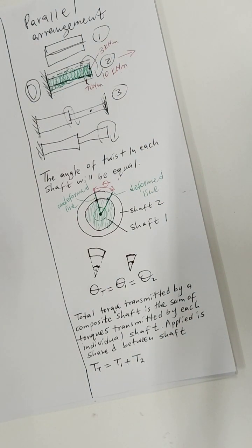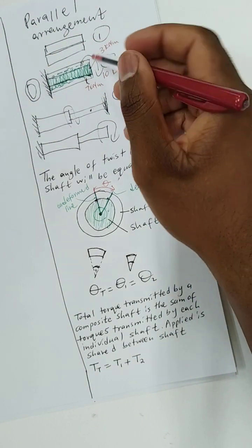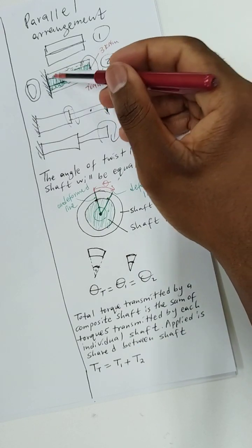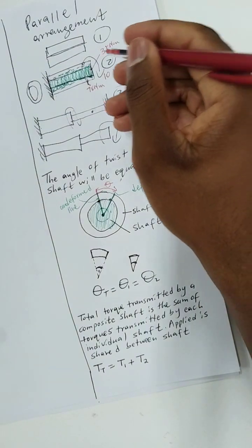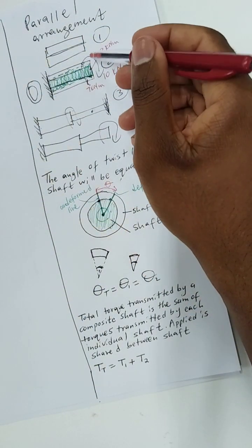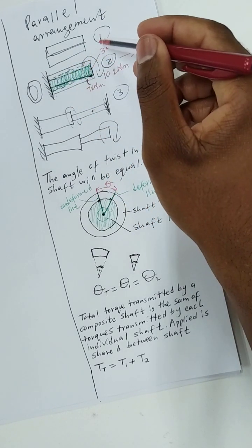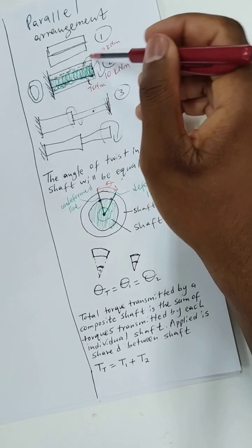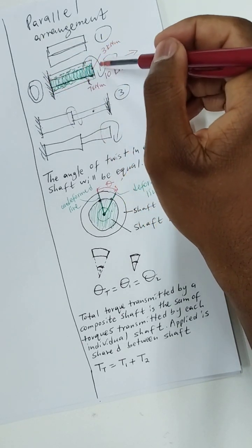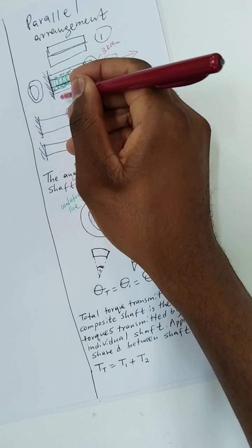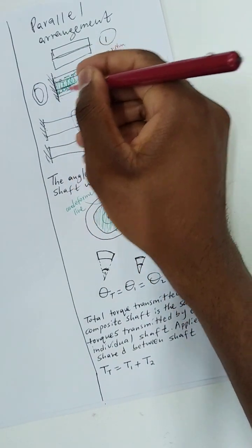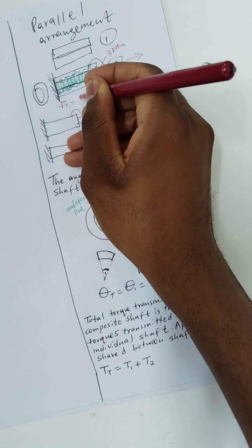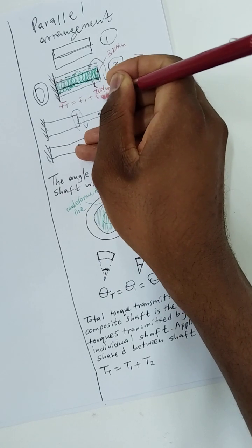In that case, this force has the impact of stretching the length, and that's where we had the X. But we know that in a parallel arrangement like this, these two components are going to share the load. In parallel, we know that Ft equals F1 plus F2.